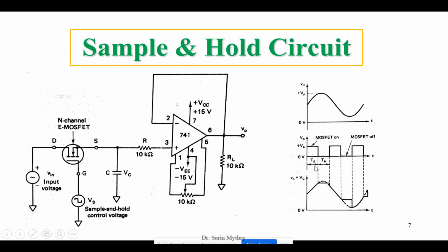You can see TS is given, TH is given. So this is the sample period. In the sample period, the charging of the capacitor is taking place. In the hold period, whatever the data is stored here will be held at the output. That is the hold operation taking place.